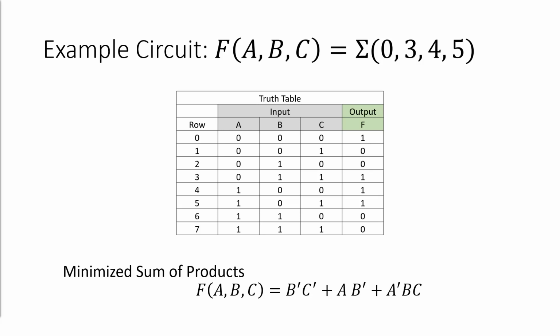So also in this lab, we're working with the concept of min terms and max terms. The sigma there, that Greek notation, whenever we say a circuit is the sum of, and we give these numbers afterwards, the numbers we've given are in base 10 decimal. That means the numbers in the sigma notation tell you where the ones are in your truth table. And you can see the truth table below. We've got our inputs, and then in the rightmost column, the output F.